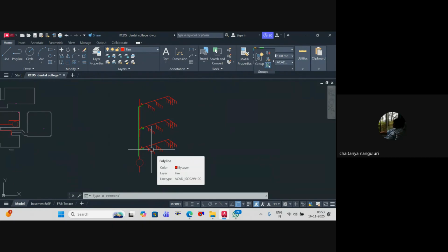No, not to the sump, because it's a rare application and the water will be very dark, because the water is stored in the MS pipe. Once you open it, you'll get black color water. So you don't mix it, you push it either to rainwater or whatever is nearest available for you, either the stormwater drain or normal regular drainage. That's how we basically connect it.